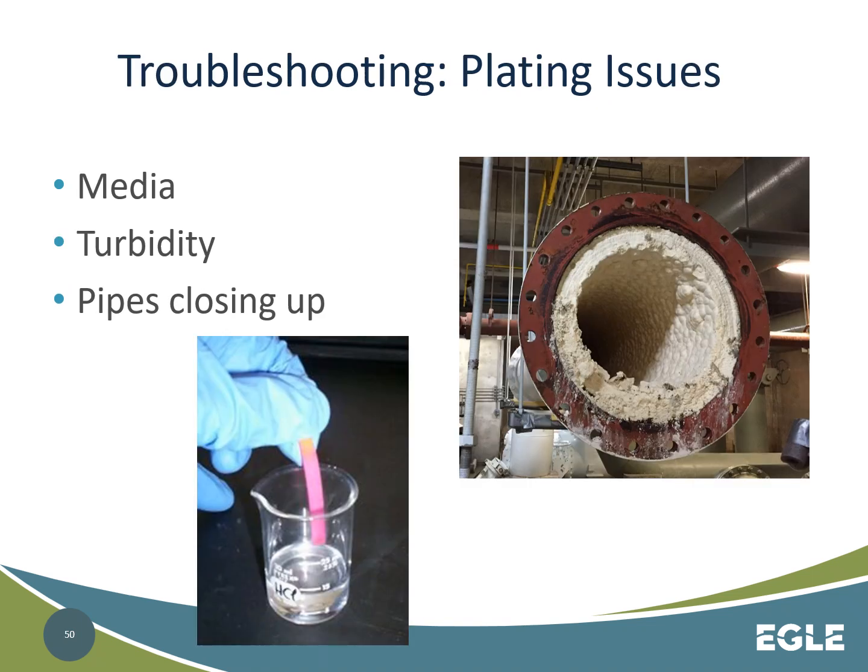This calcium plating can cause buildup on the filter media, reducing its effectiveness. It can also cause high turbidity readings. Turbidity is often used as a surrogate for pathogens, but this is difficult in a lime softening plant, since often cloudy water is due to lime sludge carryover and not naturally occurring turbidity. Because of this, regulations allow turbidity samples for lime softening plants to be acidized if they show high readings at the compliance location.